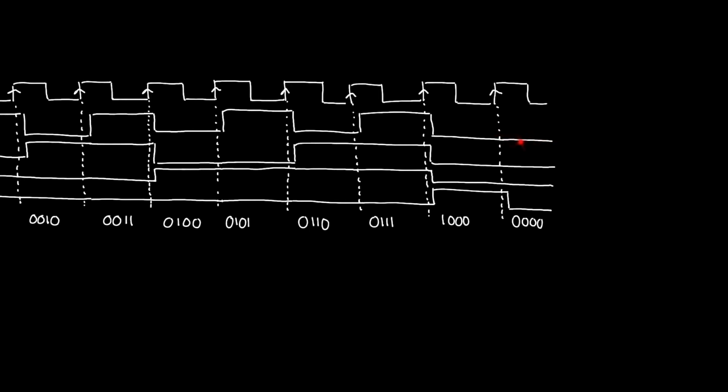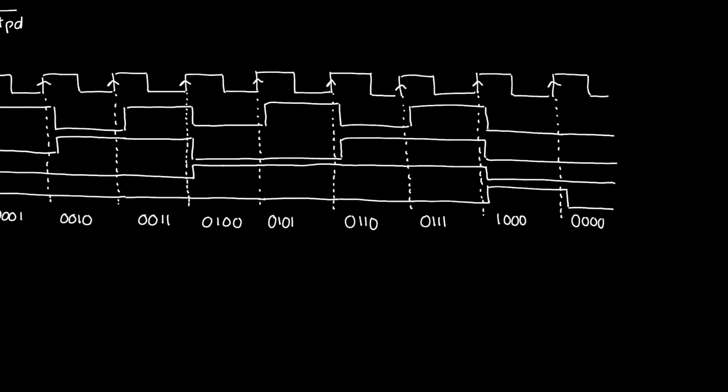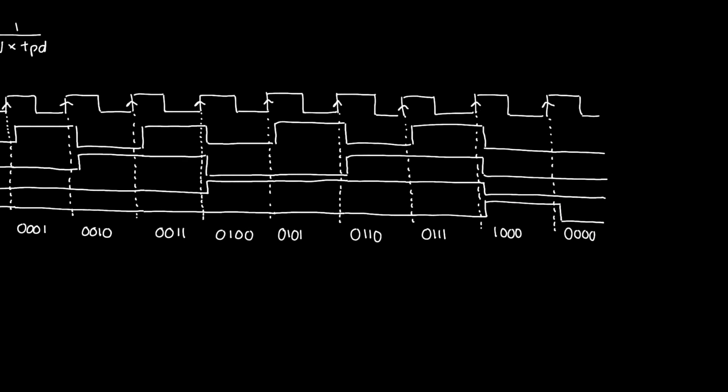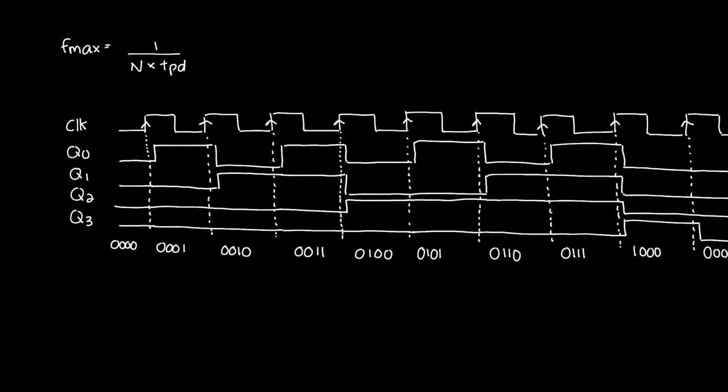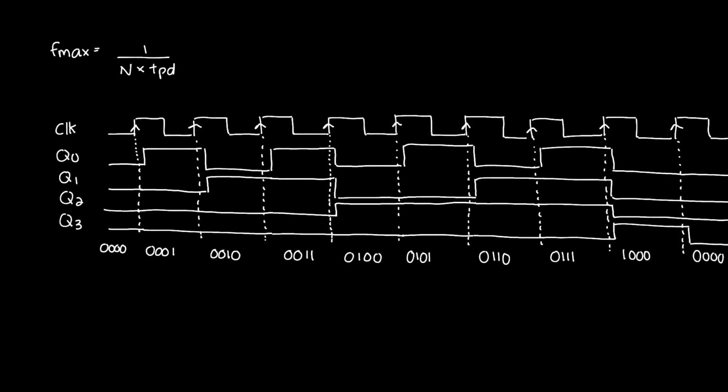And I don't have that in a synchronous counter, a fully synchronous counter, which is what I have here. So these are the two features that let me know, just by looking at the timing diagram or by looking at your waveforms on your scope. Those are two features that tell me right away that what I'm looking at is a fully synchronous counter. So that differentiates a fully synchronous counter from an asynchronous counter.